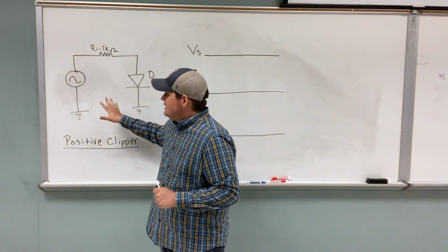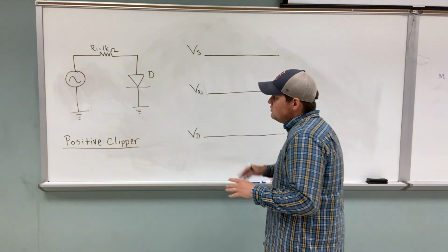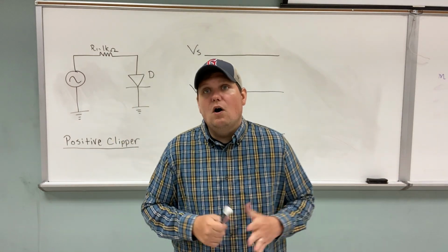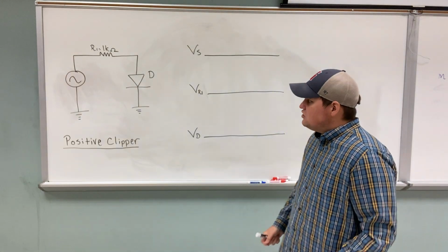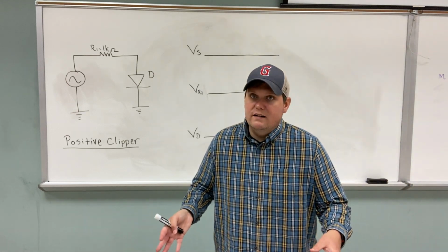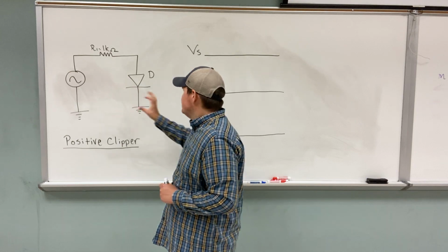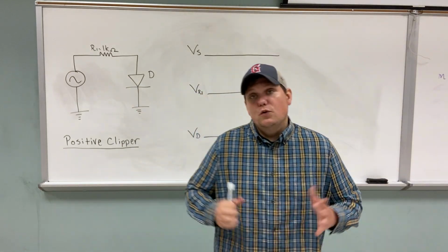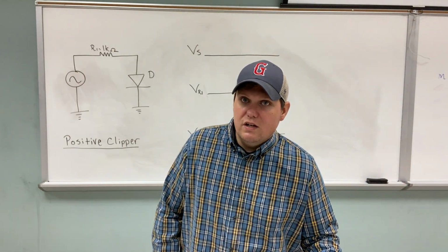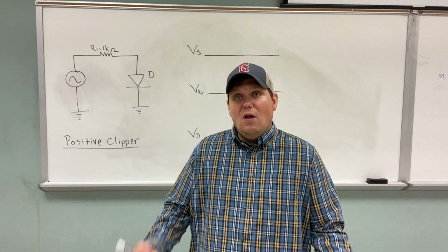We've already talked about diodes in the DC world. Diodes in the AC world are primarily used for what we call rectification. Rectification means that we are changing a signal or a quantity. So what are we rectifying? Well, we're rectifying AC to DC. If you remember, diodes will allow current to flow when forward biased, but when reverse biased, what happens? It blocks the current.